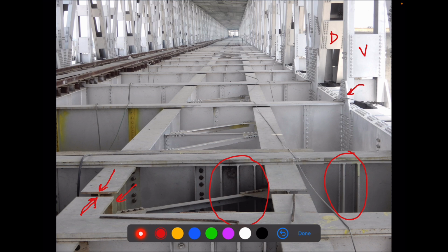Now at the end, we can say that this is the end cross girder, right? This is the end cross girder. And at these two ends there would be bearings sitting over the pedestals. As we have already discussed, for fixing the bearings you have to first lift the girder, or for some maintenance or inspection purpose, you have to lift the girders.